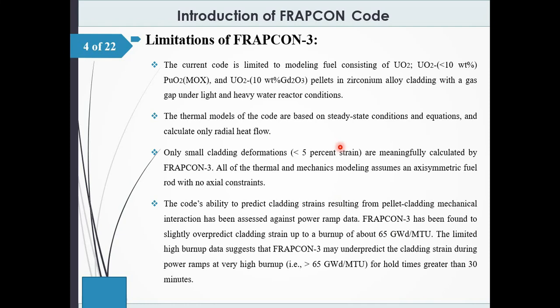activities in the reactor. The limited high burn-up data suggests that FRAPCON 3 may underpredict the cladding strain during power ramps at very high burn-up, for burn-up greater than 65 gigawatt-days per ton of uranium, for hold times greater than 3 minutes.